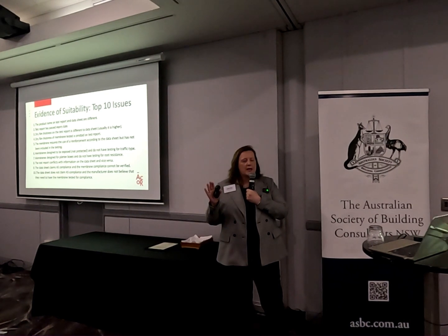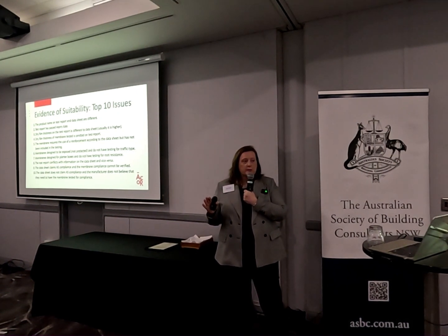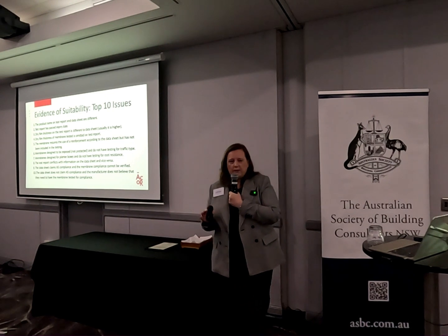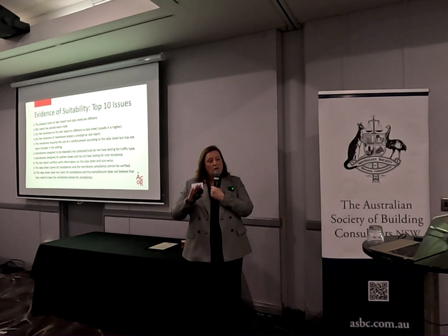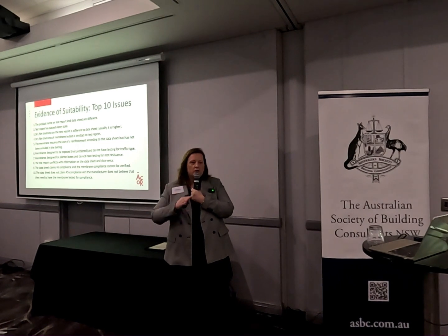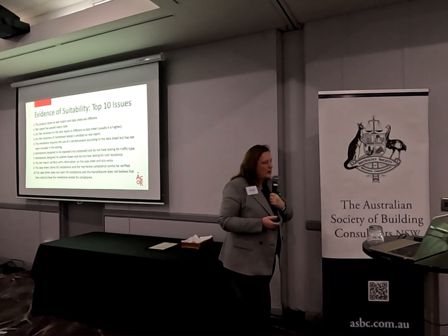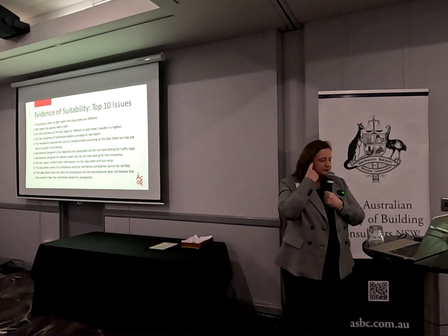I don't think that any of the ones I've seen to date where reinforcement is on the data sheet has actually been tested, or at least it hasn't been clearly stated on those test reports. There are a lot of materials that don't need reinforcement, but there are still some manufacturers where that is their practice, and they're not testing with that reinforcement. So if it is something that is optional, depending on a certain situation, then you're going to need to test both, because the materials will behave differently. If you've got a reinforcement fabric inside a liquid membrane, they're going to behave differently. So that's one other common thing that I've seen.